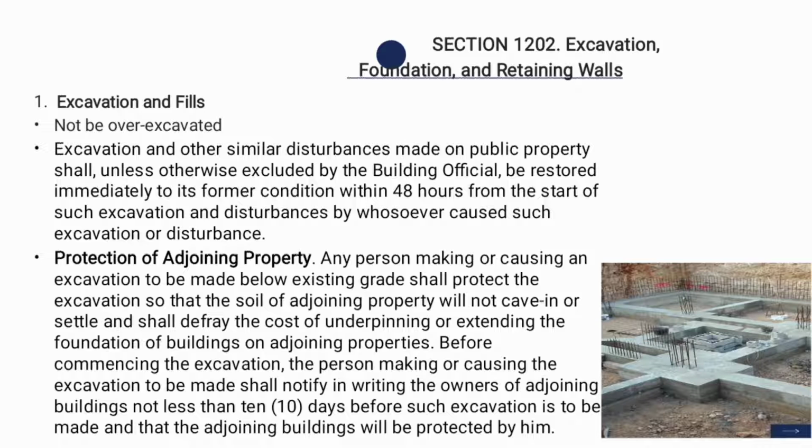All of the process must be accepted and follow engineering practice. For the excavation and fills for buildings, one thing that needs to be considered is that the excavation works should not affect or result in danger to any property or occupants, and it should not be over excavated.